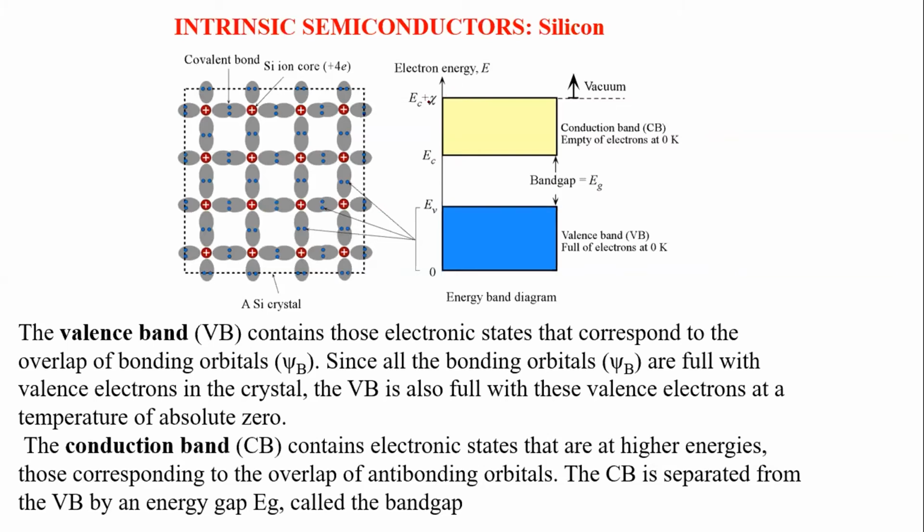In the case of metal, normally we write the work function. Here we are writing the electron affinity, which is from the bottom of the conduction band to the vacuum level. Metal is slightly different, where you call it the Fermi level; from the Fermi level to the vacuum level. So this forms the intrinsic silicon band structure.